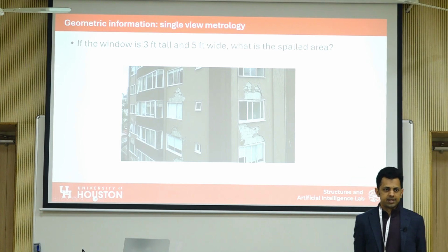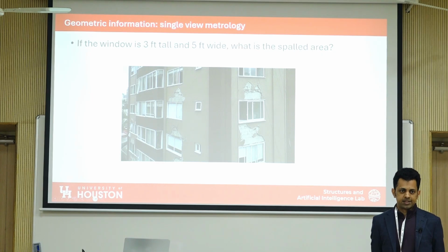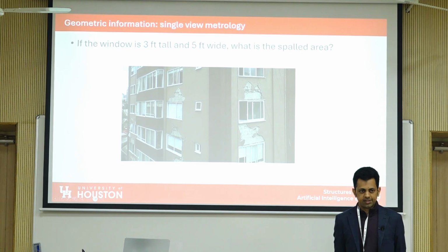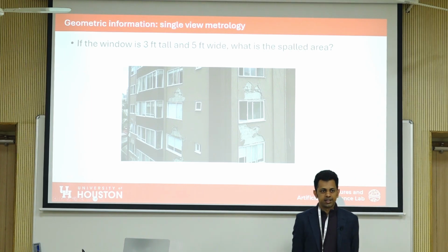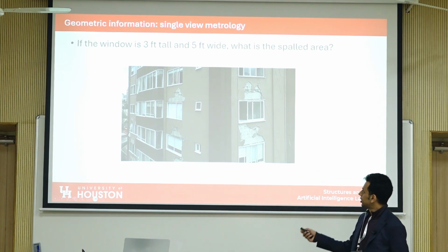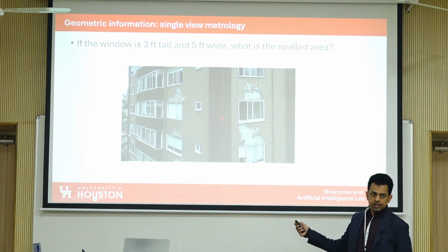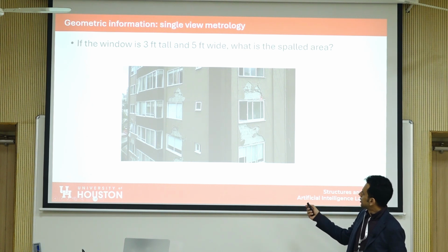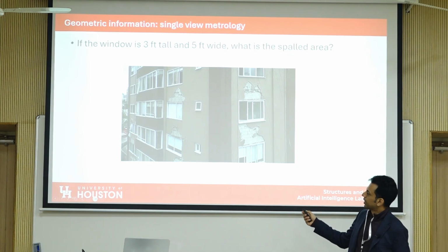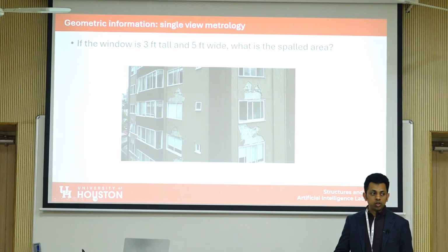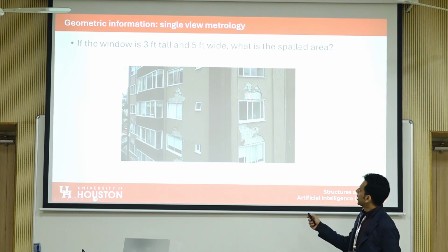Yes. So the pixel length at the far end does not scale to the actual length. It's just something that you need to take into consideration, because the spalling area here will have fewer pixels than the spalling area here, even if they're the same size. So you need to take that into account if you have to accurately measure.